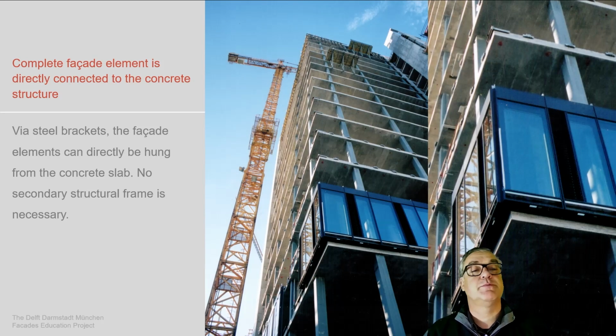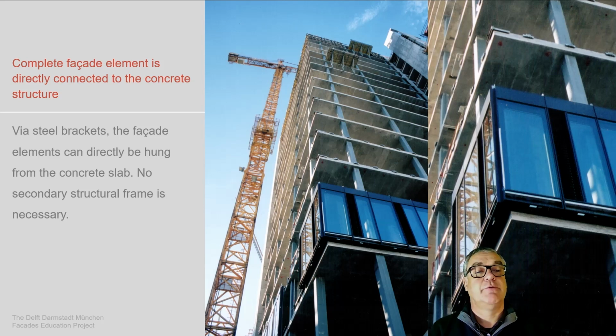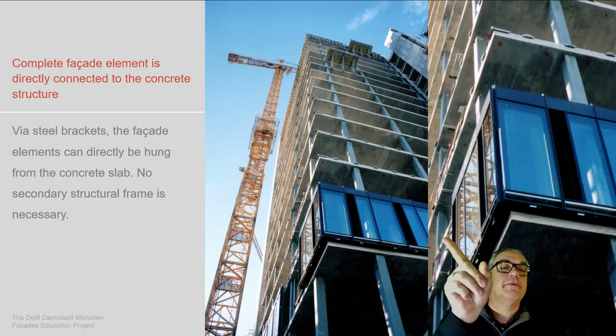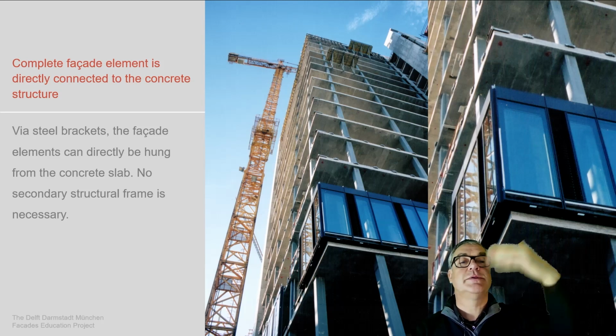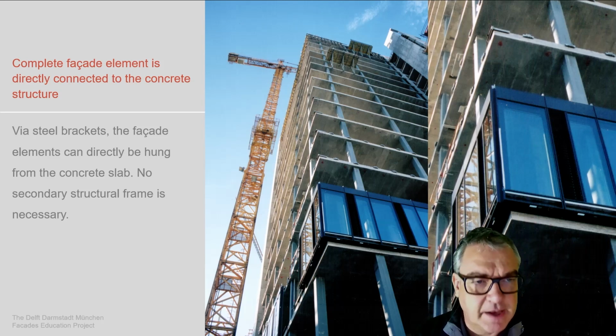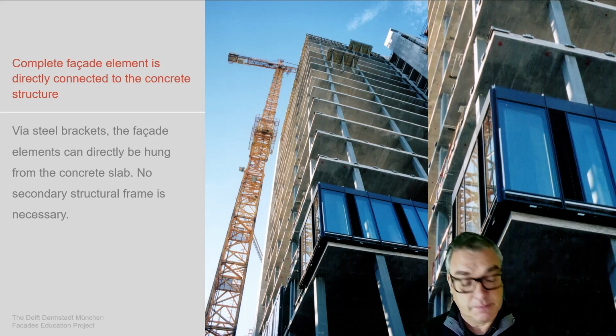We can also see this in this high-rise building. You see the first floor is done with unitized facades already, and then you see the brackets on top of that. On the next two floors the brackets are already fixed, and the ones above are not yet fixed, and they're still in construction with concrete work quite at the top of this building.